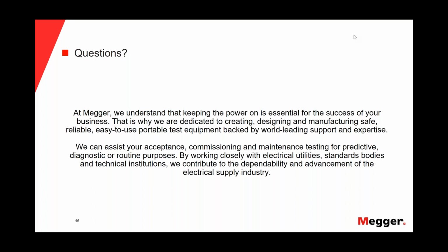And then from an operational standpoint, let's just say you're doing that test and at a splice or an accessory, you now see PD at the levels where you want to start questioning whether or not you should replace those. Then you can go into the damped AC, which is a pure diagnostic, to verify that that is PD you're actually seeing before you commit to actually repairing that. So it really just depends on what it is you're trying to do during that test. Damped AC is pure diagnostics. The CR with the VLF will be the accompanying PD with very low frequency during commissioning testing.